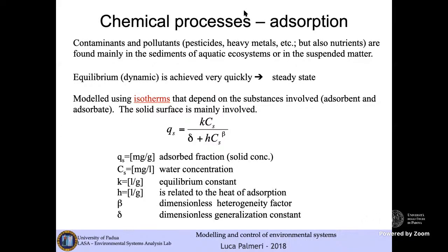condition is quickly achieved. As we have anticipated, these processes are modeled using isotherms, but it depends on the substance involved, the adsorbent, and the adsorbate. The adsorbent is the substance that adsorbs the material, and the adsorbate is the adsorbed material. This is essentially a surface process, so the solid surface is mainly involved. And the very general model we may employ to describe this surface process is the one that I have written